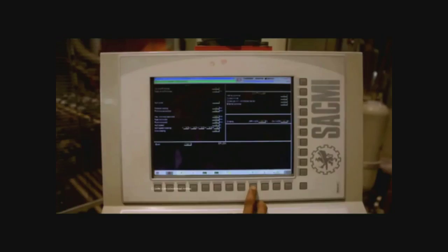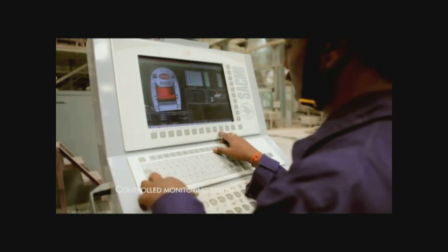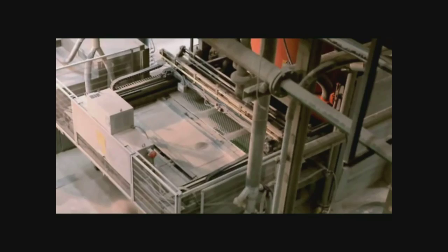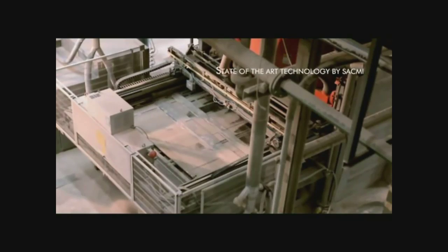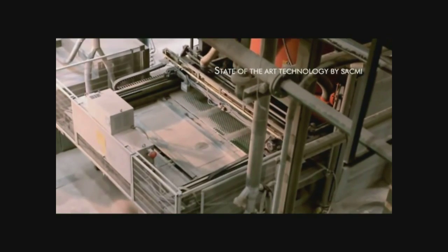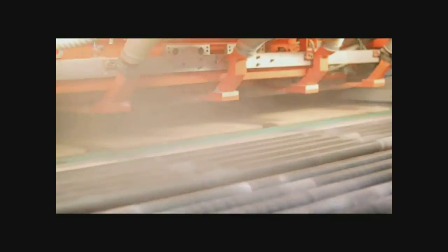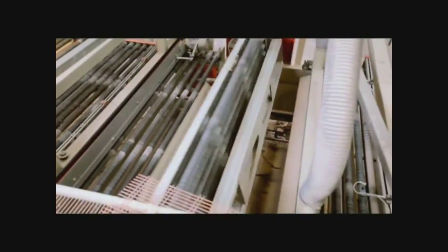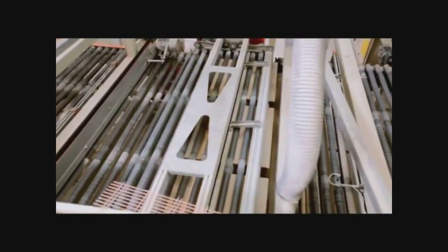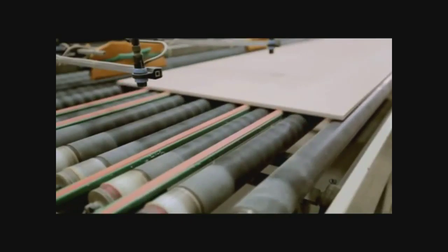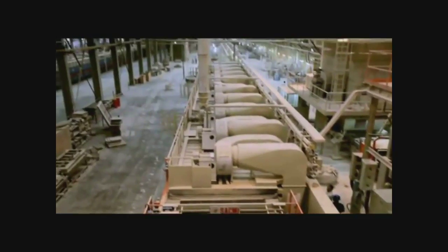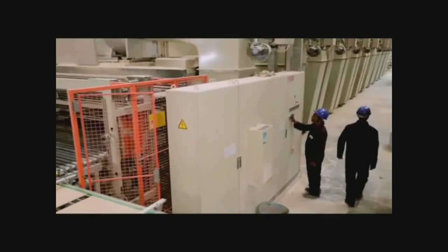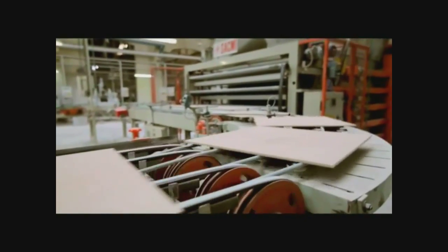Made by Sacme, the world leaders in tile technology, our fully automated tile press is capable of shaping tiles in a range of sizes and shapes. The machine presses the powder at 400 to 500 bars of pressure to create a raw green tile. This green tile is then processed in a dryer, completely removing all moisture content, making it ready for the processing that will truly give it color and finish.